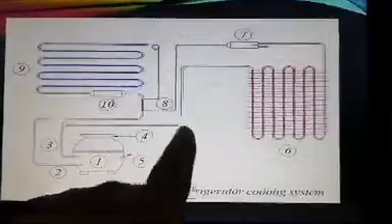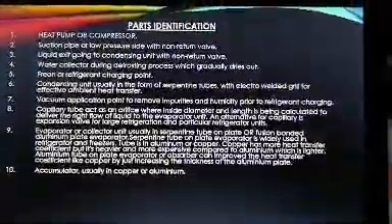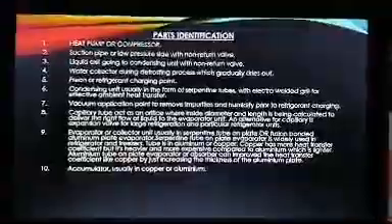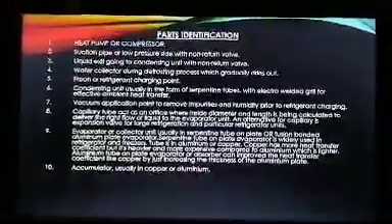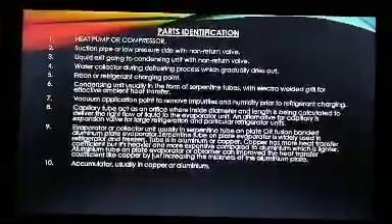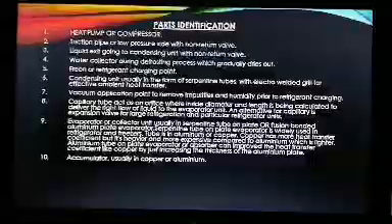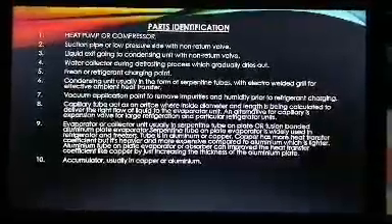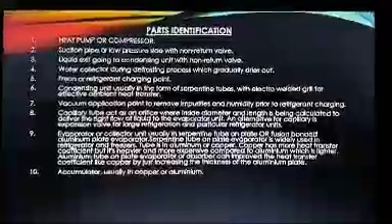Number 8, capillary tube, which acts as an orifice where the inside diameter and length are calculated to deliver the right flow of liquid to the evaporator unit. An alternative to capillaries is the expansion valve for large refrigerant and particular refrigerator units.